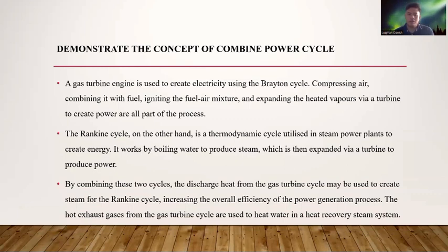By combining these two cycles, the discharge heat from the gas turbine cycle may be used to create steam for the Rankine cycle, increasing the overall efficiency of the power generation process. The hot exhaust gases from the gas turbine cycle are used to heat water in a